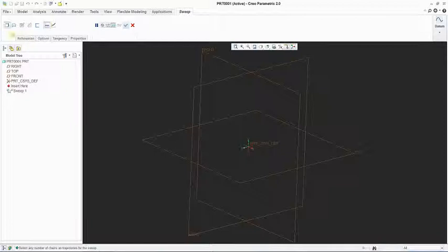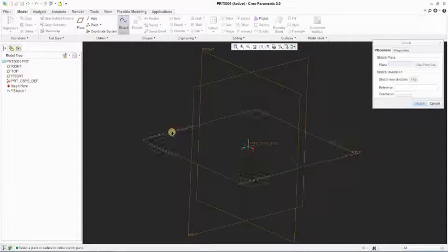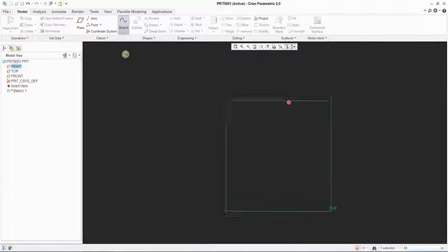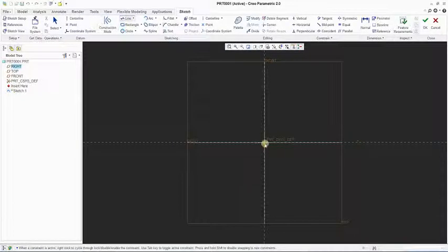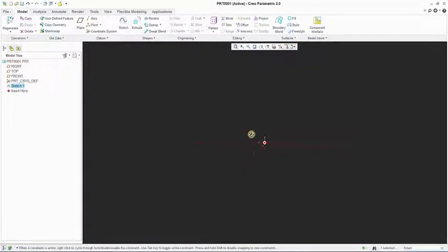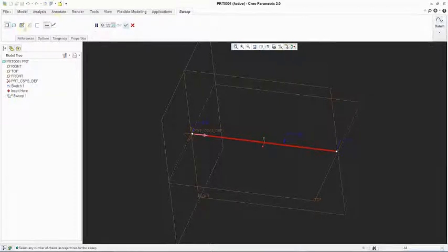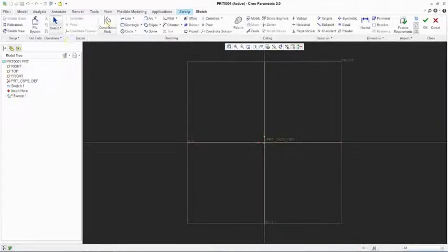So let's say, no, sorry, before this, let me create a path. Sorry about that. Okay, now we have a line, let's say somewhere around 1000, whatever length. I have a straight line here. I'm going to take sweep, select the profile, and do a sketch. Select this.